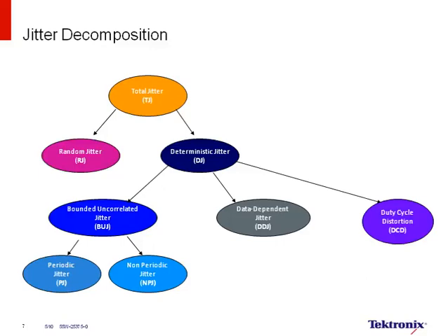The second reason for the decomposition is root cause. Understanding how the jitter is decomposed allows one, in a system evaluation, to determine what the root cause is. So generally, RJ factors come from silicon processes. Generally, data-dependent jitter, like ISI, comes from bandwidth limitations in the channel.